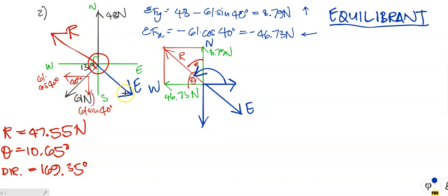The equilibrant there, which is equal to the resultant, remember the resultant has the same effect as those two forces there. If I put the equilibrant there to act along with that force and that force, this equilibrant will balance out those two forces there. What does it mean? It means that this point here ain't going anywhere.